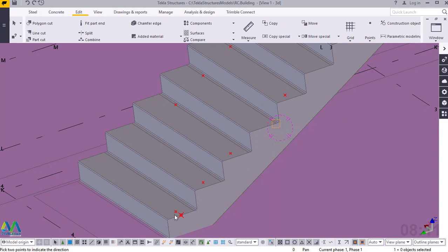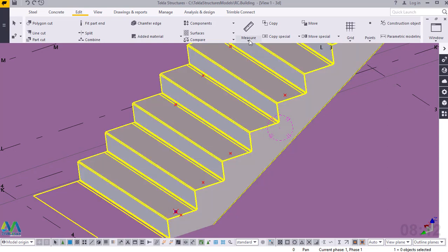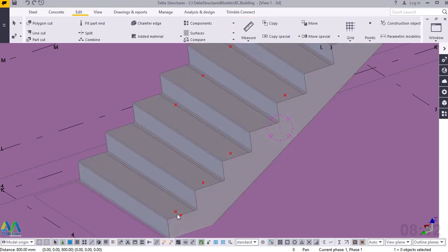So the moment you've done that, you click on these. We want to offset these points up by 800. We want the height of our handrail to be 800 from the thread level. Now from here to here is 800. We can verify that or counter check that. I'll snap on the bottom here and snap right here, and you can read it from this end. It is 800 millimeter. Same.